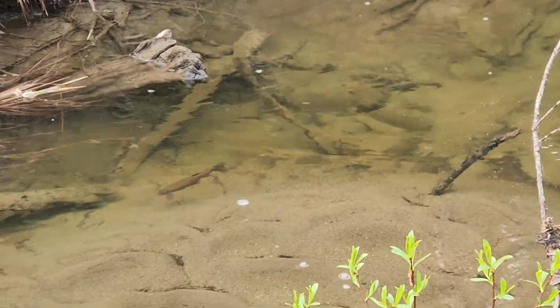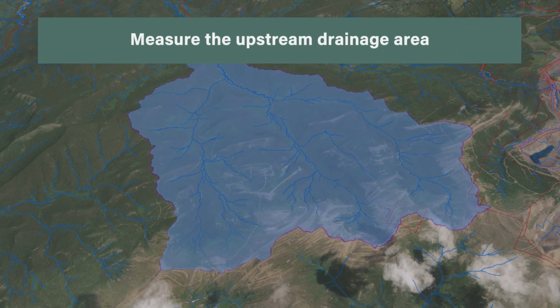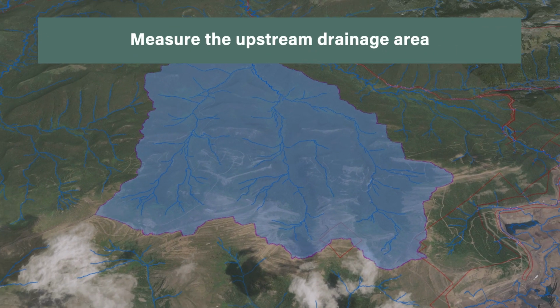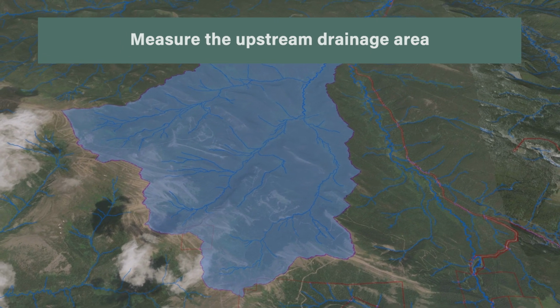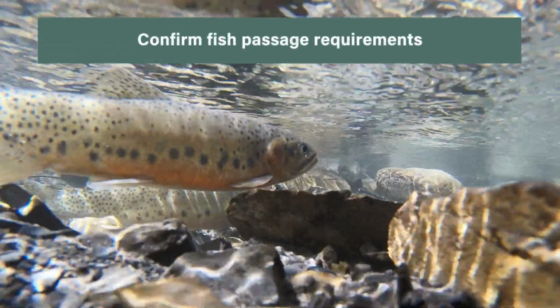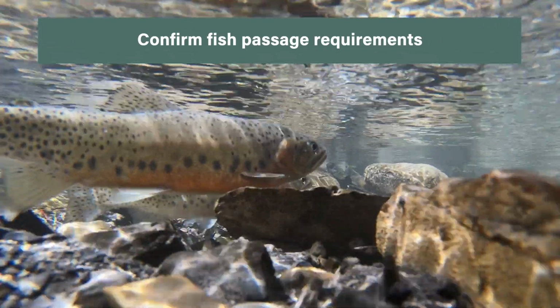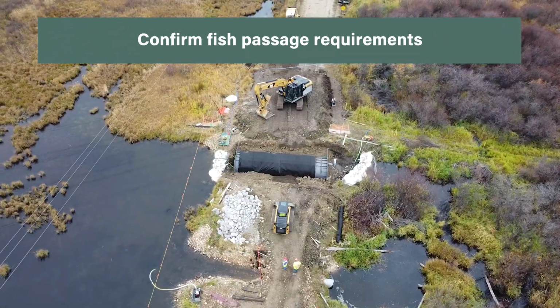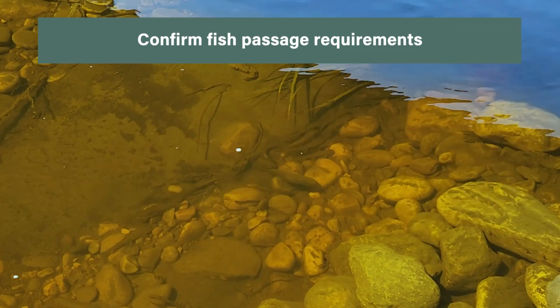The general process for completing the hydraulic design is as follows. Measure the drainage area and channel characteristics upstream of the watercourse crossing based on topographic information. Confirm the fish passage requirements for water velocity and depth related to the potential flow conditions, the length of the structure, and the target fish species life stage.